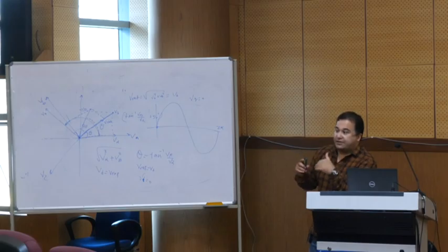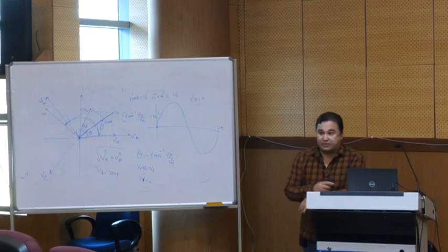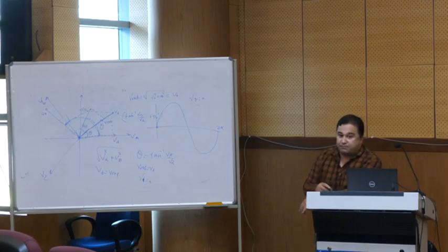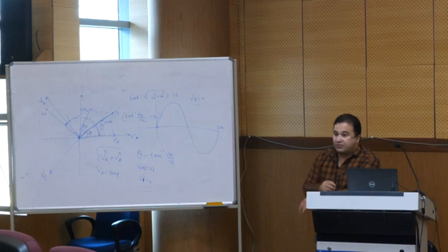But then you have the sinusoidal value, and making a reference for the harmonic is a little bit challenging. You cannot separate it. So it is better to go first to Park and then jump to Clarke to separate the alpha from the beta. There are different methods you can use, but the most straightforward way is with D and Q, because this decoupling is not that complicated.